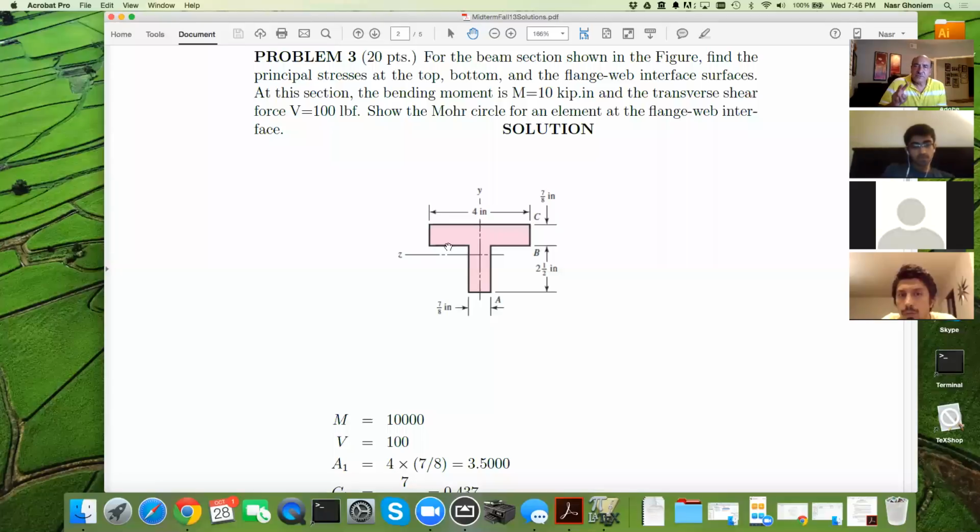And therefore, you have two types of stresses. You have a tension or compression, and then you have a shear. And in order for us to evaluate the maximum shear, we have to combine those in the way that we've learned to find principal stresses or to find the maximum shear. So let me review here now.